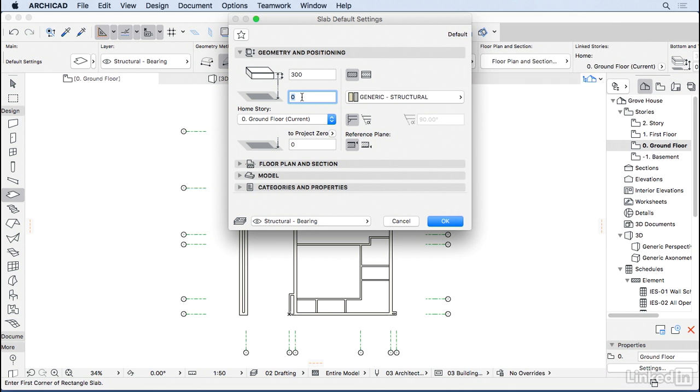Here you can choose the thickness of the slab and the height to the floor that we are right now. So we are at the current floor, and the top of the slab, as you can see here in the arrows, it's at the level 0 compared to our current floor. You can also add an angle to the edge of the slab. Let's keep it straight for now.